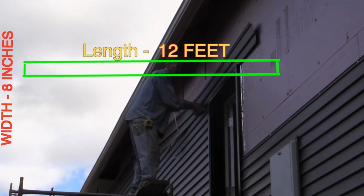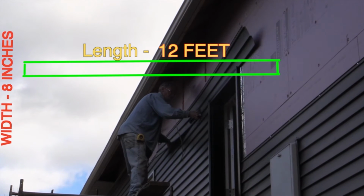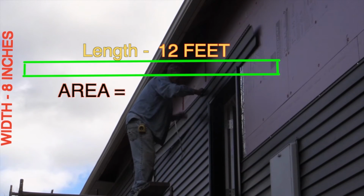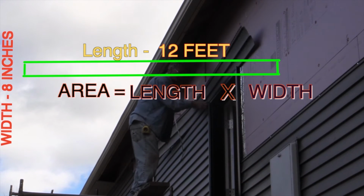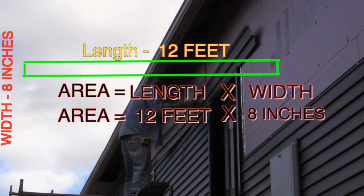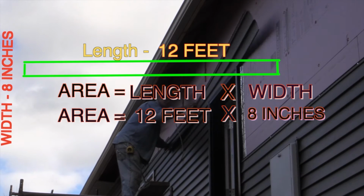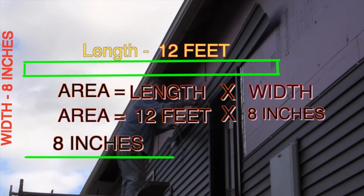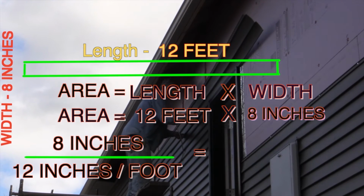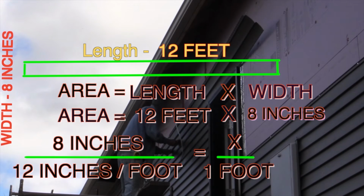Alright, let's start by determining the area for a single piece of the vinyl siding. Because the shape is a rectangle, we can use the formula area equals length times width. The length is easy, that's 12 feet, but the width is 8 inches, so we need to convert that to feet also. 8 inches is a part of 12 inches, and is equivalent to what part of a foot? We'll use x to represent the unknown part of a foot we are solving for.